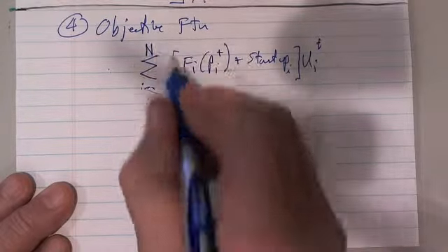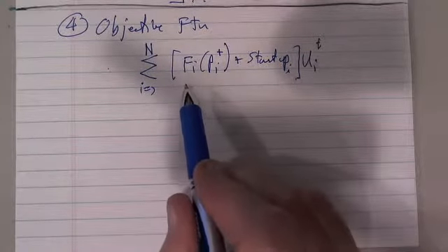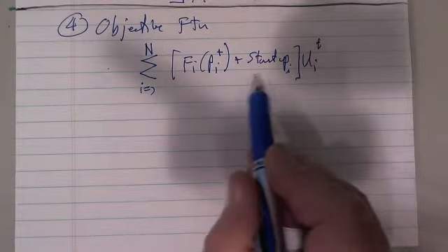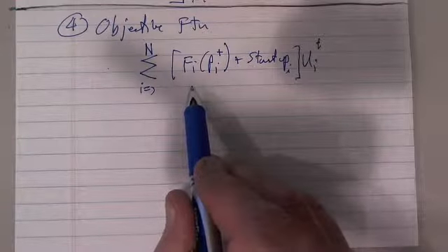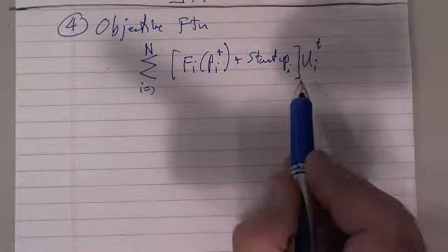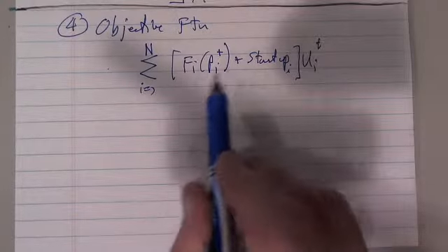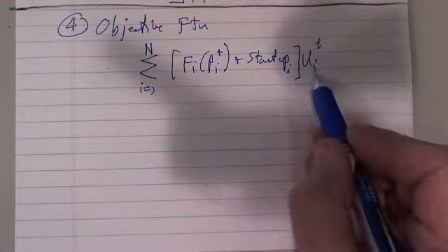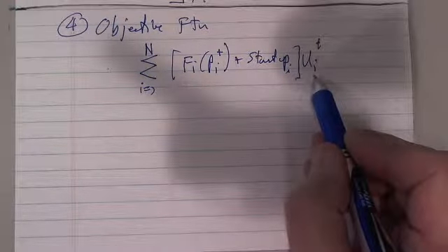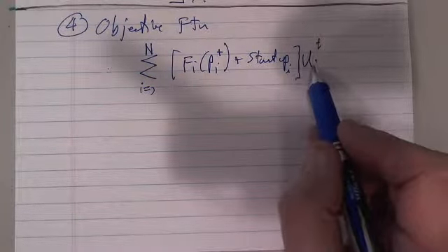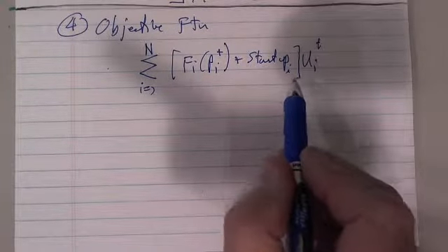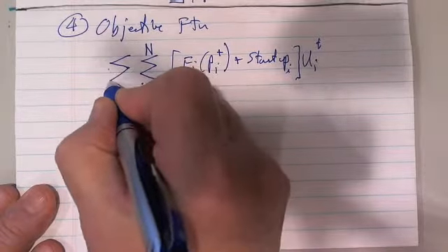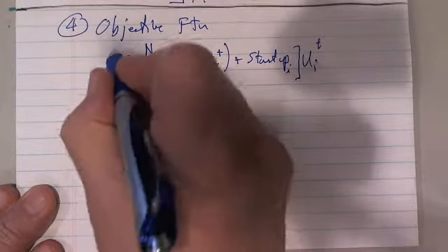Now that is the economic dispatch program. What am I minimizing? Well, not economic dispatch. I'm not looking at startup, but this is the cost to operate in a particular hour if I started the unit up. And this is the economic dispatch if the unit is going to be on that hour, ui of t equals 1. If ui of t equals 0, well, there's no cost contribution. And then I have to minimize that over t equals 1 to T.